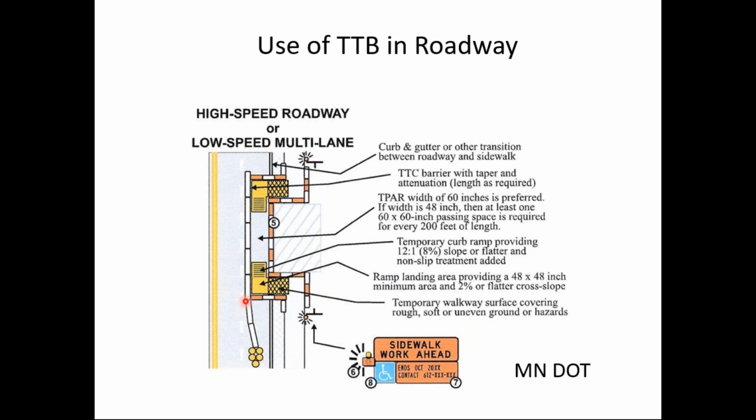But now notice separating the pedestrian path from the vehicular traffic are the temporary traffic barriers, the concrete barriers, the crash-worthy barricades. And of course, as we just mentioned, the ends of these are a hazard for motor vehicles. So they have, looks like crash cushions here to shield that exposed end. And then the pedestrian would go up the temporary ramp, and the pedestrian channelizers would direct them back to the sidewalk.